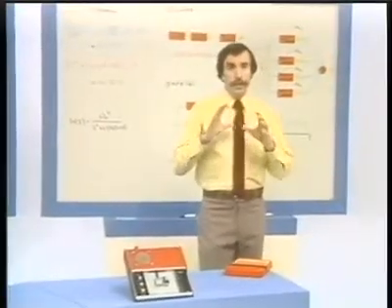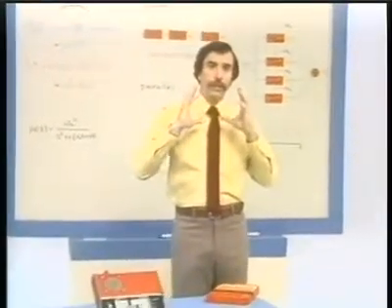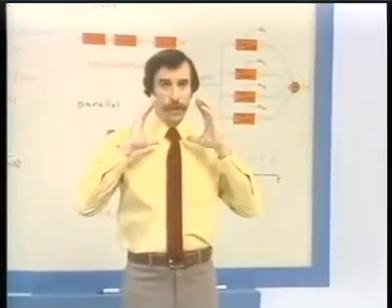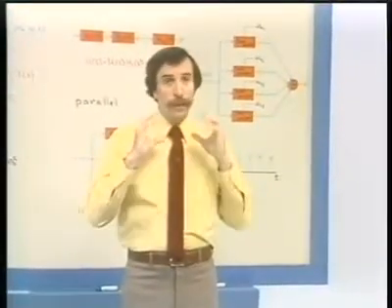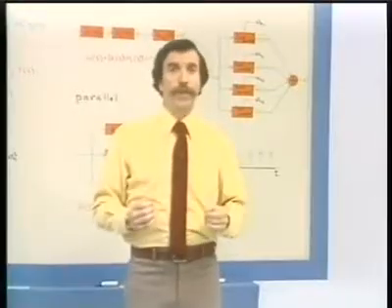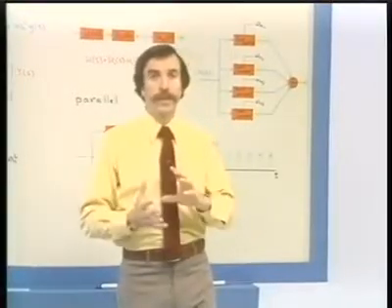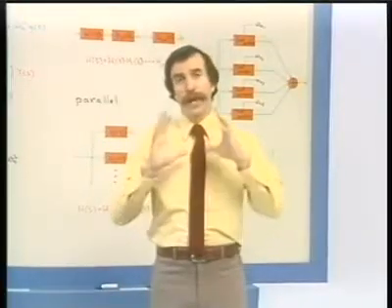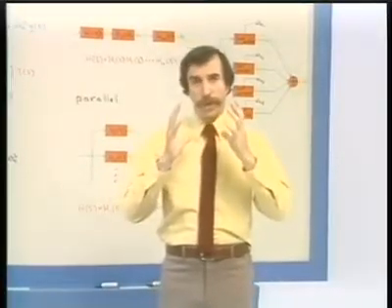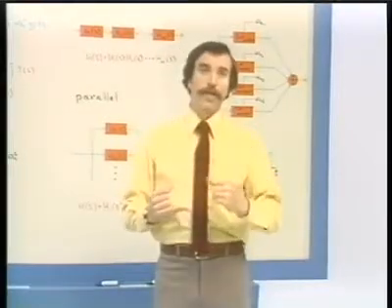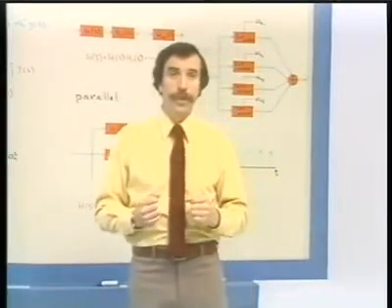In speech synthesis, of course, what we're trying to represent or implement is something that corresponds to the vocal tract. The vocal tract is characterized by a set of resonances, and we can think of representing each of those resonances by a second-order system, and then the higher-order system corresponding to the vocal tract is built by, in this case, a parallel combination of those second-order systems.